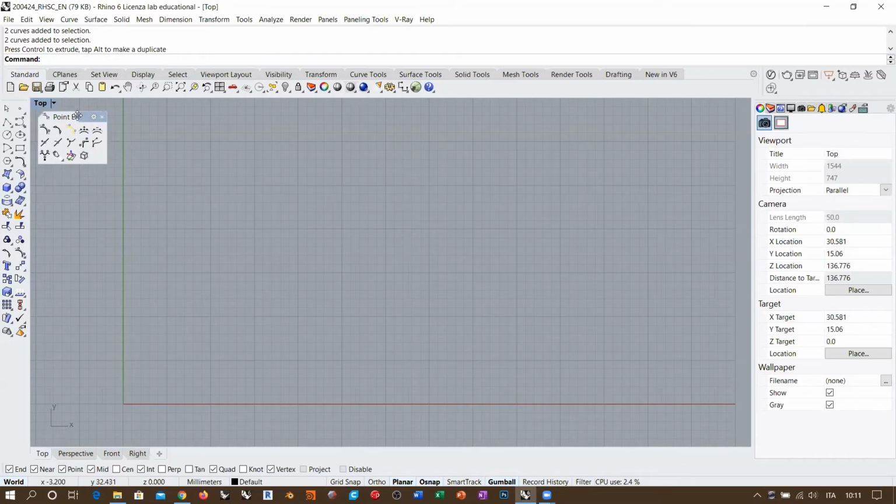I will be using Grasshopper for this, but create a control point curve, which is relevant in order to control the speed. Degree 3, which is the default, and I'm going to activate the grid snap in order to draw with some rule.